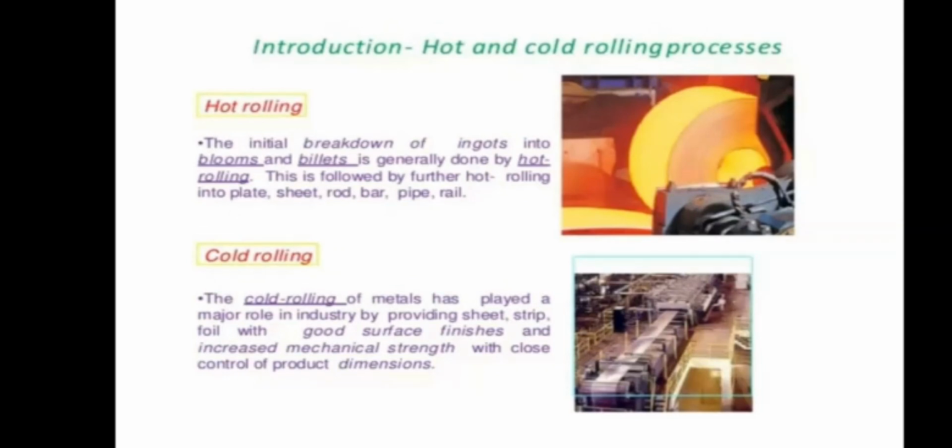Okay. You see hot rolling of strips is shown in the upper diagram. The lower diagram shows cold rolling, where a series of rollers will be provided, where you see the sheet metal is flowing on the conveyor, on the channel only. There you will be having different setups of rollers. The rollers will apply the force. Because of the cold rolling, strain hardening will take place. As a result of strain hardening, the material property is also enhanced.